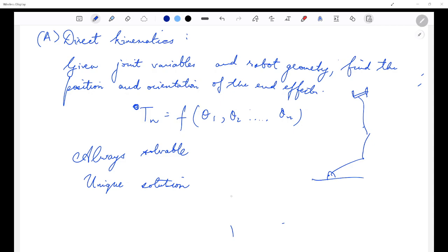For example, if there is a 2R robot, the L1 and L2 links matter, and you cannot bring the robot into this range if you have joint angle limits here. If you do not have them and it can collapse, it would be able to come here. But if you have joint angle limits, which we usually have, you won't be able to cover this. So we'll have a question in workspace as well.